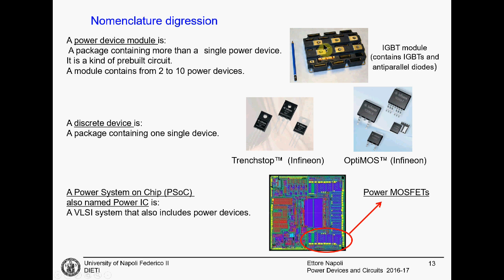These screws here are for connecting the wires. The wires are not small wires just to carry the signal. These are usually bars of copper that are thick like this to carry a lot of current without a lot of power dissipation, without a lot of resistance, and with a minimal amount of parasitic inductance. This is another problem.